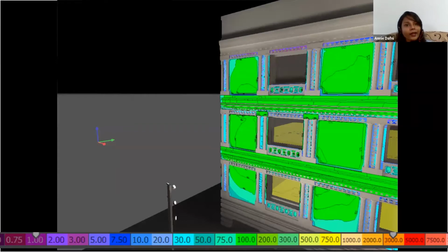So there are a lot of factors which we need to consider while deciding lighting for any facade. And one such is the ambient lighting condition. If you have your building set amidst a very crowded city which has a lot of street light and lighting from other buildings, then naturally in order to make your building stand out, you need to increase the lux level, and the recommended levels will be more than 100.